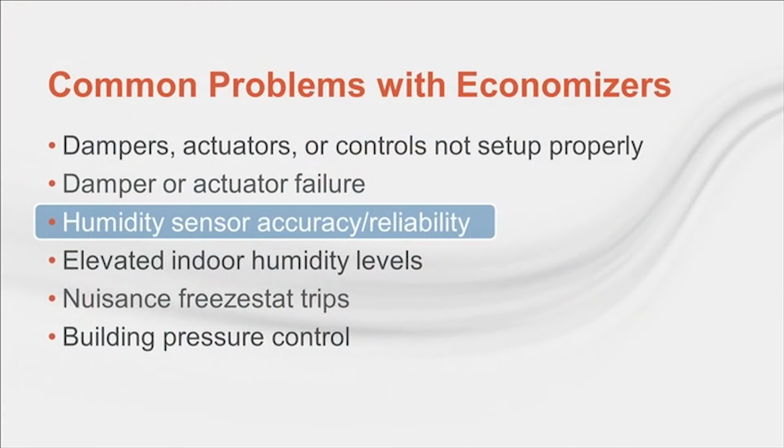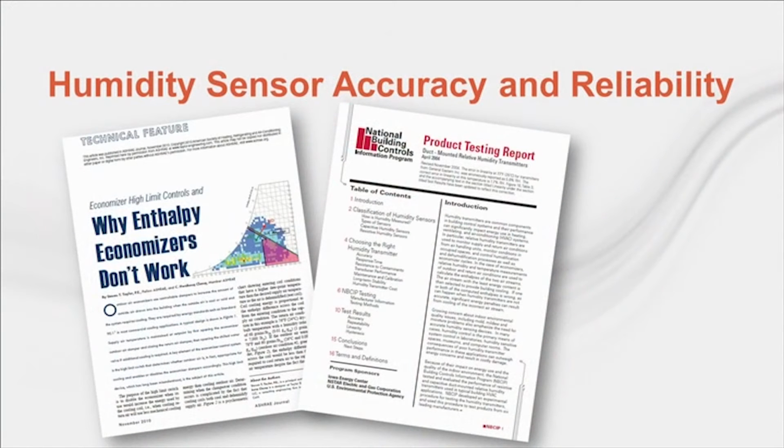Next, while sensors that measure dry bulb temperature tend to be stable and remain accurate for years, humidity sensors have often been notorious for requiring frequent calibration. For this reason, an economizer control strategy that relies on the measurement of humidity must consider the possible inaccuracy and ongoing maintenance requirements. Some engineers have proposed that any additional energy savings from enthalpy-based control might not justify the ongoing calibration requirement. Obviously, this depends on a number of sensors being used.